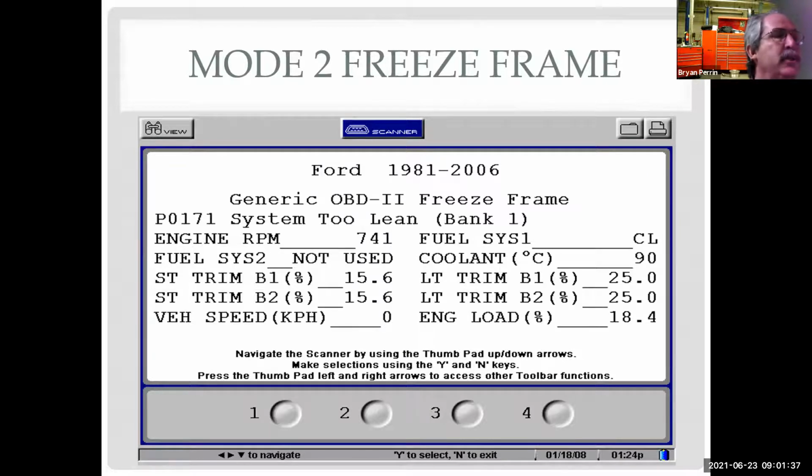So in this case, I'm looking at a mass airflow sensor vehicle with high fuel trim values at idle. Vacuum leak. Because if it's a mass airflow sensor, my engine speed would be higher and I'd be going down the road. If it was a fuel pump problem, my engine speed would be higher, my vehicle speed would be higher, and my calculated load would be much higher. So the most likely cause is a vacuum leak.